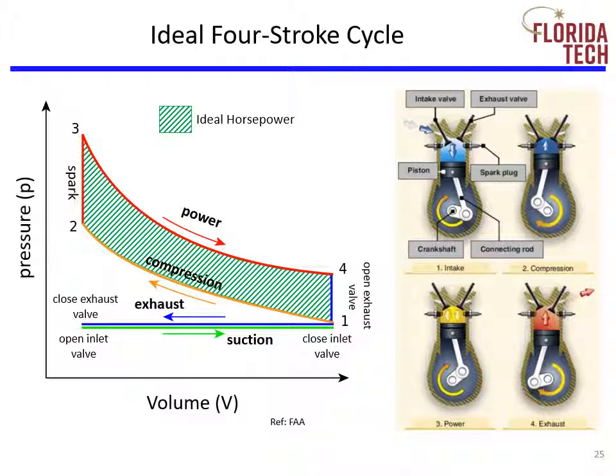On a typical four-cylinder engine, each one of the cylinders is in the middle of a different stroke. That way, one cylinder is always in the power stroke and the engine is able to keep the crankshaft rotating, thereby allowing the remaining cylinders to go through their respective strokes. As we saw in these four strokes, there are two valves at the head of each cylinder that are opened and closed to allow the fuel mixture in and the exhaust gases out.